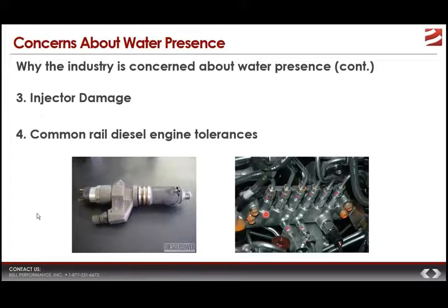They are marvelous pieces of engineering. They have very little tolerance for water. In fact, the manufacturers of these engines specify that they want as close to zero water as possible. So there's plenty of reasons to worry about water. And since it's universally present in storage tanks, we need to talk a little bit about how to detect it and then what to do about it.